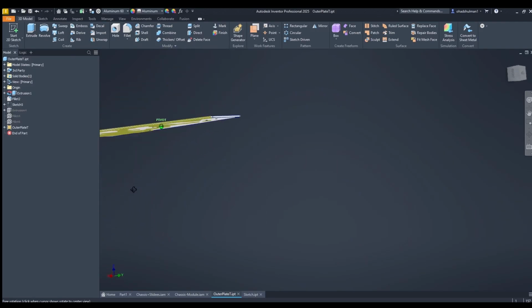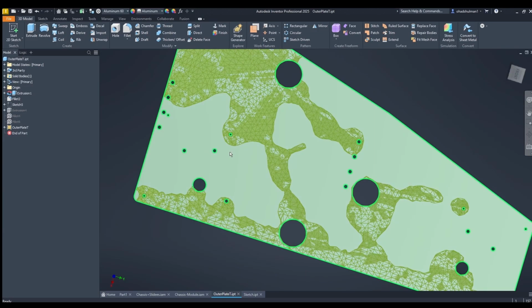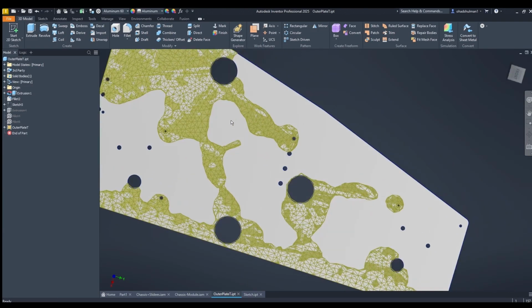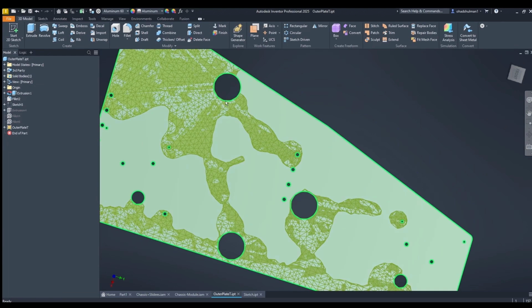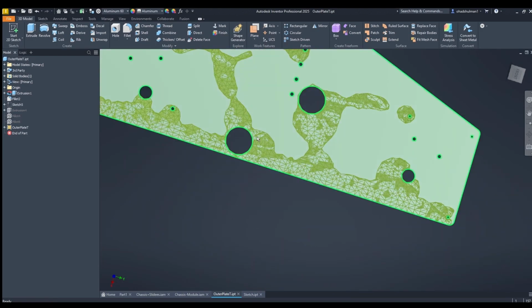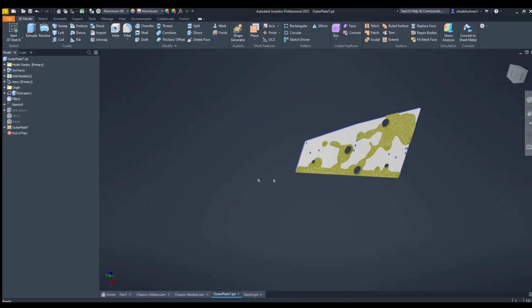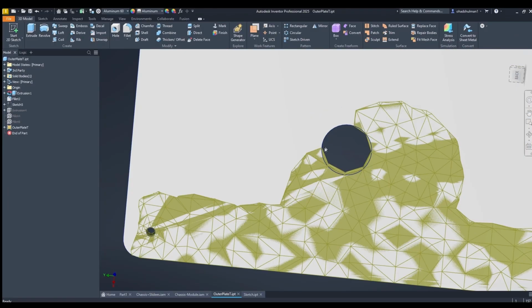And you can promote shape, which gives you this yellow thing. Basically wherever it's yellow is the weak places, and where it is not yellow is the strong places where you can be aggressive. And you can see it shows that little corner that's bended in the stress simulation, and that bearing that also bended, you can see that it depicts those as the weak places. So this is in line with what we saw at the stress simulation.